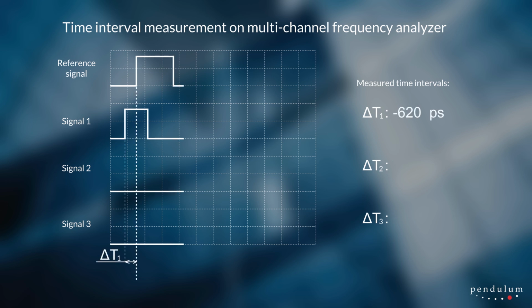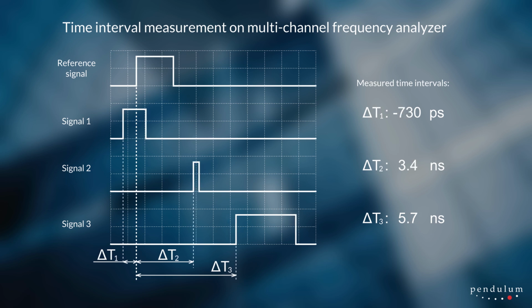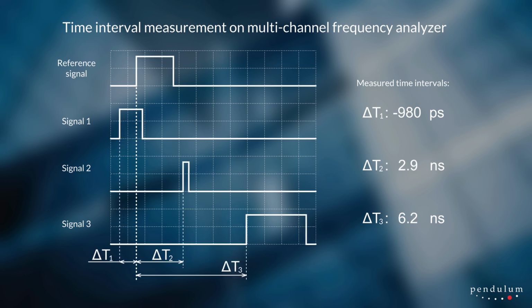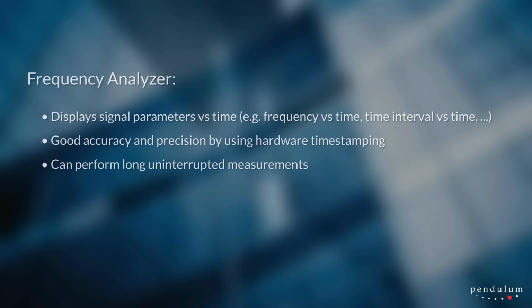Modern frequency analyzers supplement this with multiple independent input channels, performing high-resolution and high-speed gap-free measurements, real-time statistics, interactive graphs, and other features. Since waveforms are not recorded and not stored in memory, it becomes possible to observe the signal parameter variation over a long or even infinite time.